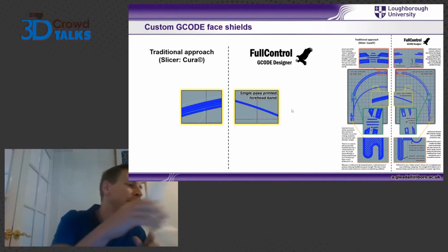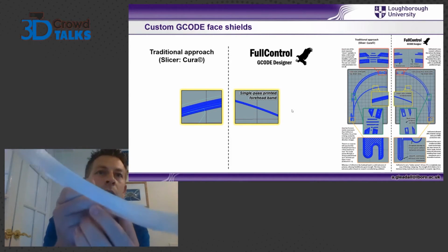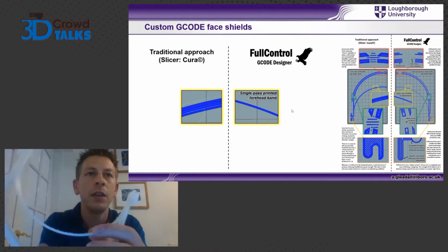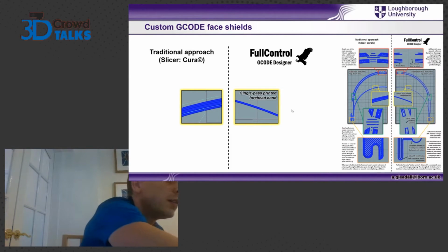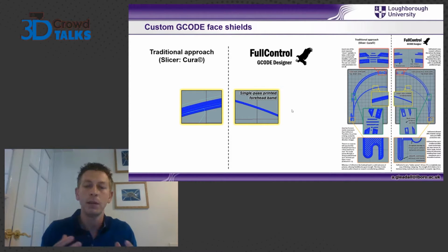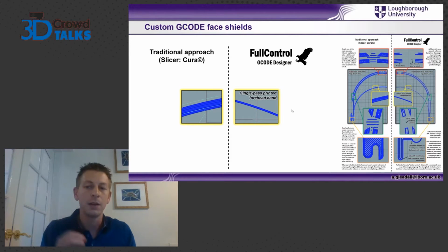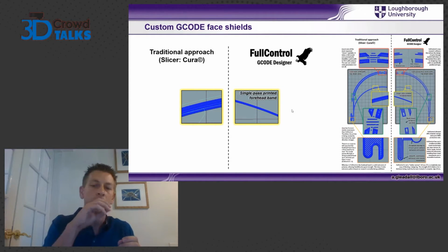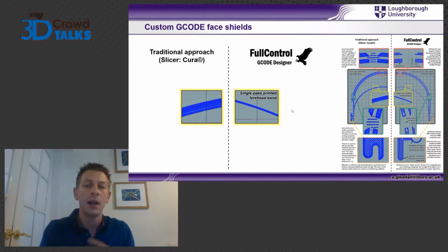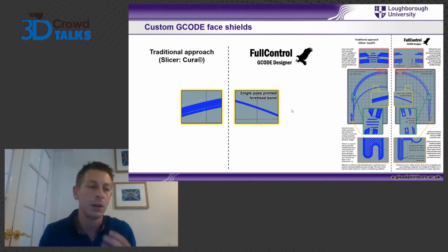There was a real problem because this forehead band, I don't think you can see that clearly, but it's really rough on the ones that were produced with slicing software. And it didn't matter if you told the slicing software not to travel outside the print path and stuff. Even when the nozzle followed the arc of that headband, that forehead band, to move to another section, it was over depositing, creating these bumps and vibrating up and down, and it was still a messy structure. So post-processing took ages sanding that forehead band to be nice and smooth.